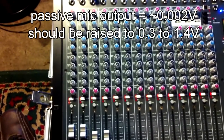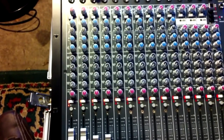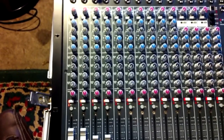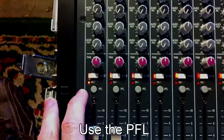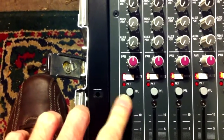Generally we'll have to turn up microphones quite a bit. So we're going to use the preamp at the first stage to get everything up to that 0 decibel ideal signal level. And the easiest way to do that on a mixer like this would be to use the PFL, the pre-fade listen button. So what I'm going to do is just show you how to use it using one of our wireless mics. You will want to start with your gain all the way down, and then for that given channel hit the PFL button, and you're ready to start looking at the metering section.